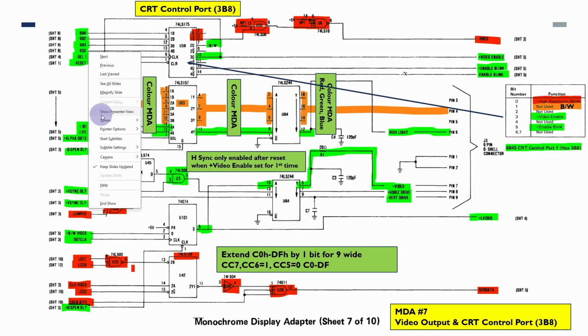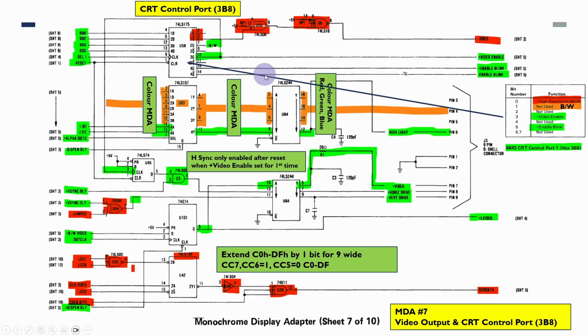Where this output then comes, this is actually sending the data out to the D connector that goes to the monitor, with whether or not we've got highlight, whether the intensity is enabled. We've got the video output here, which is whether it's 1 or 0, and then we've got the horizontal and vertical sync. And what we can see here is the alpha dots here enables this multiplexer here providing the highlight. B and W video provides the output going to the video here, and this also comes back to the status register. So this output here also goes to the status register.